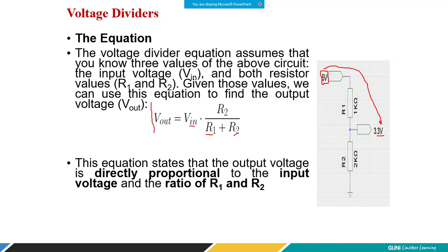Right, you can ask me a question, why is this the requirement? For example, let's say I have an Arduino board and I'm giving some voltage, and let's say I have 5 volt available from, for example, the Arduino board. It could be different, but just to give you an example, at a specific part of the circuit I cannot give 5 volt as it is, otherwise that device or that component may burn out.